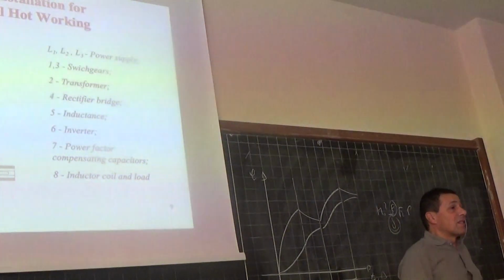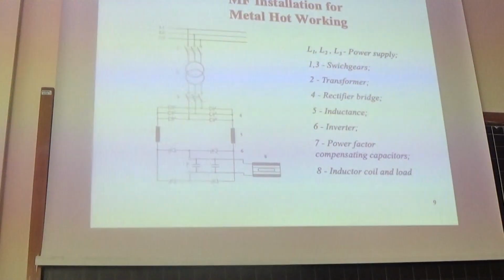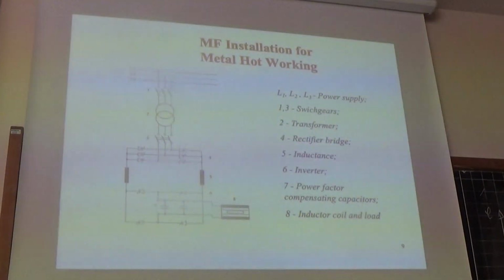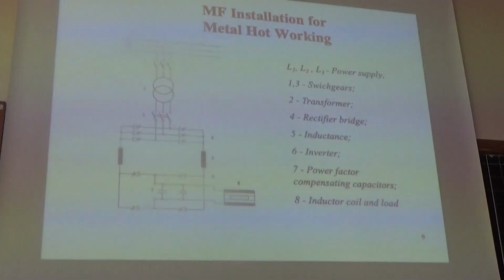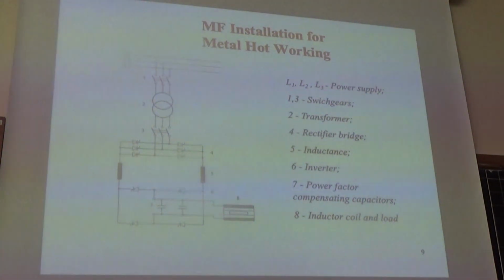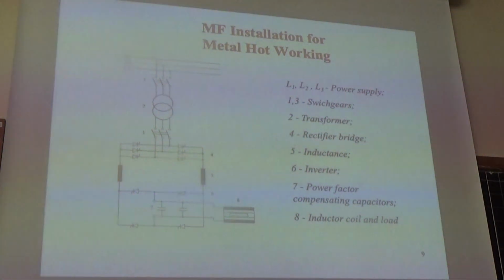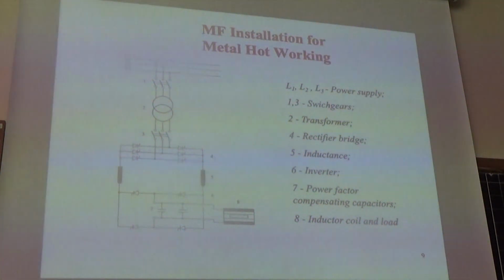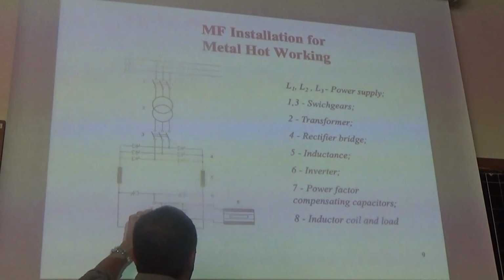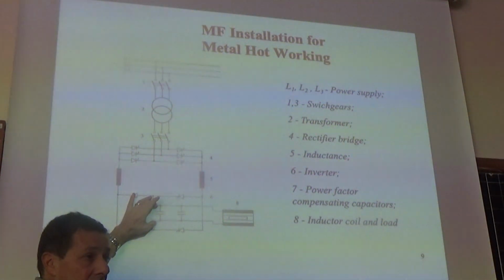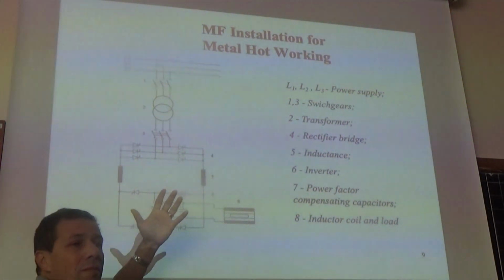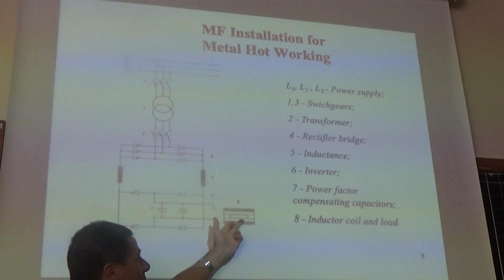And this is the typical installation that you will have in order to perform such a kind of process. Usually we have the mains, then we have the transformer, rectifier, and the inverter. So, rectifier, inverter, compensation capacitors, load matching circuit, and then the inductor.